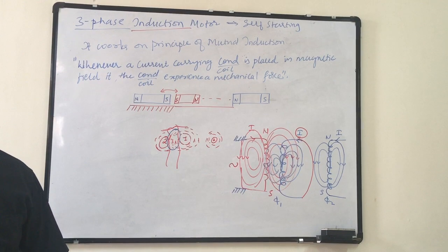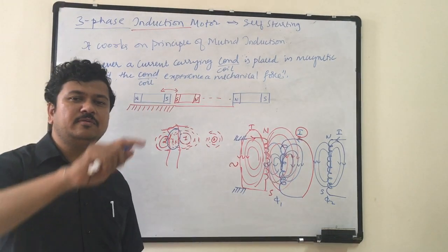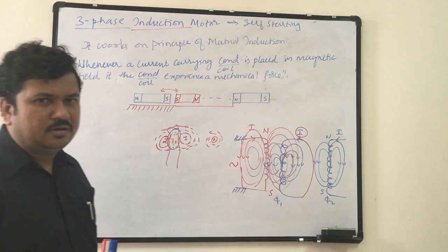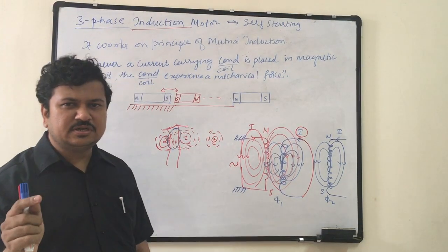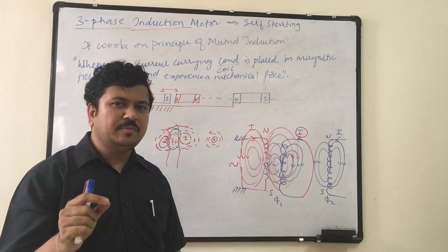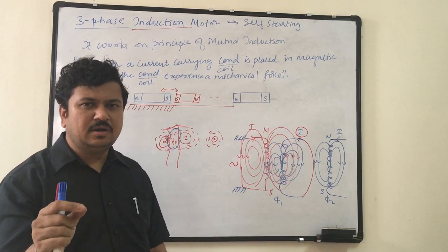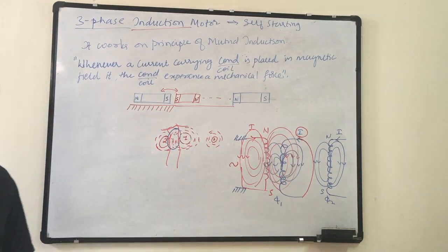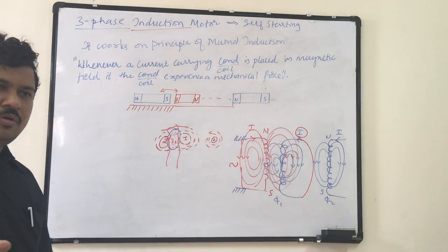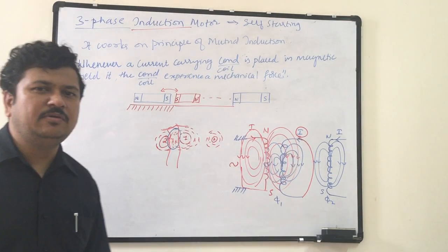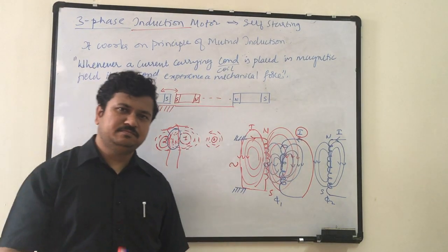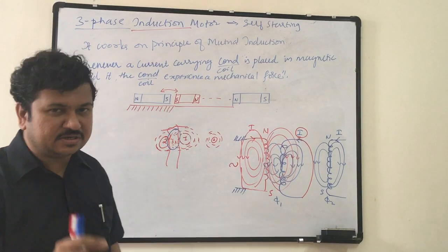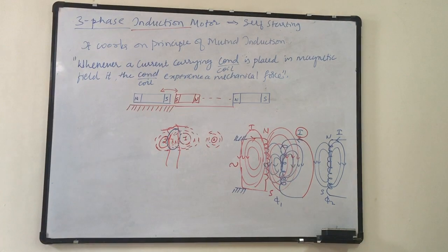Between one coil and the second coil, therefore there will be an air gap between the stationary part and the rotating part. Okay, there will be air gap between stationary part and the rotating part, and that air gap will be so minimum, it will not be crossing more than 2 to 2.5 mm for the largest of the machines. The water pump what we see in our house is having air gap of less than 0.5 mm. You can imagine the gap between stator and rotor less than 0.5 millimeters. So small gap is given there.